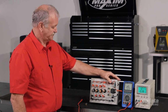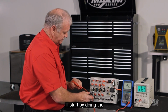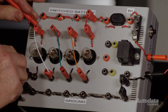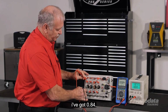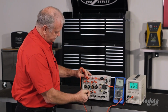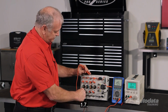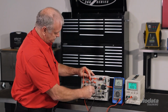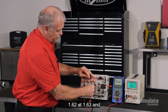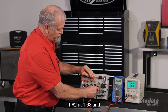Let's check. I'll turn the circuit off. My meter's set up on resistance, and I'll start by doing the resistance of each globe. I've got 0.84, 1.7, 1.62 and 1.63.